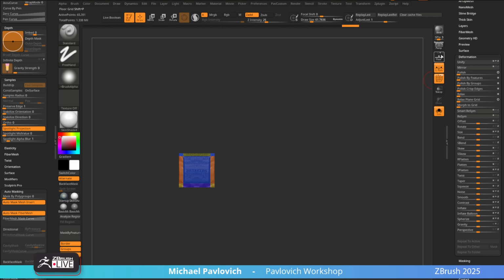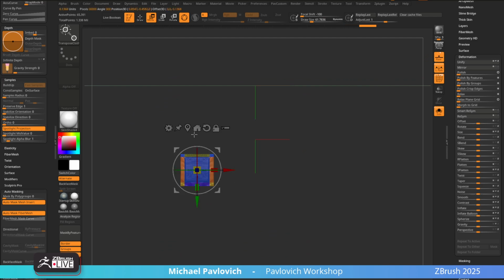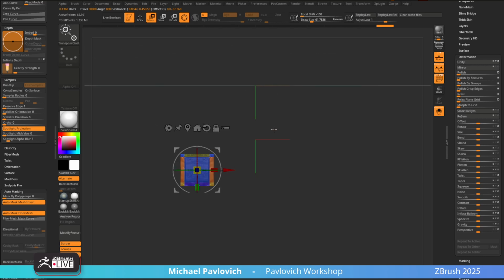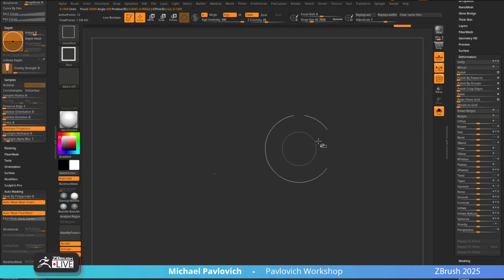And the reason why mirror is being weird is because, again, we're just working out here in space based on that image. You know, if you wanted to, you could hit W, go to Unmatched Mesh Center, hit Home. It'll put it right back into world zero, whatever. That's totally fine. There's nothing wrong with that. I might even do that on the next one.